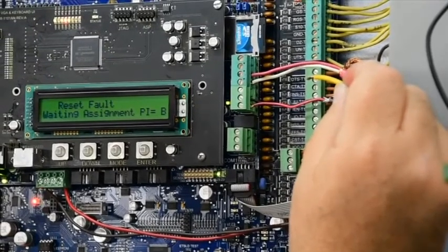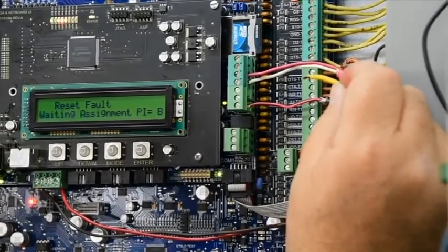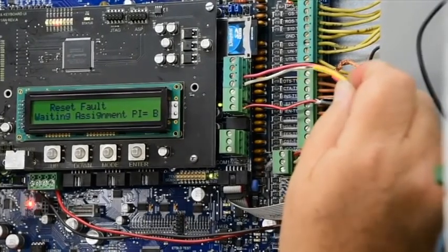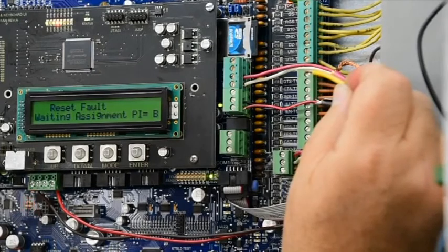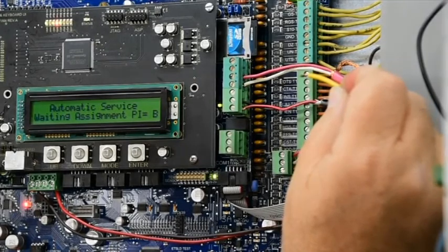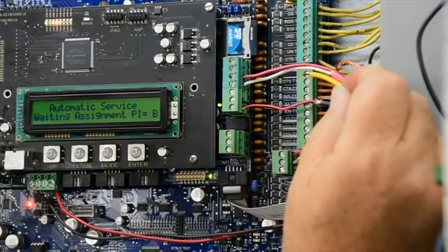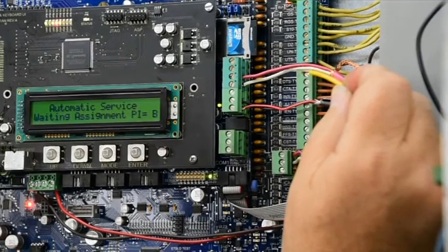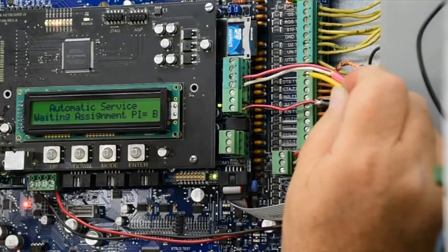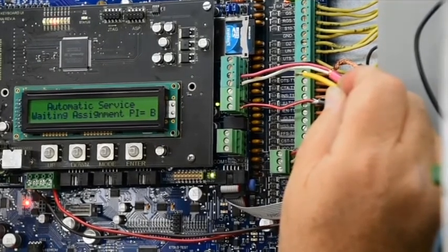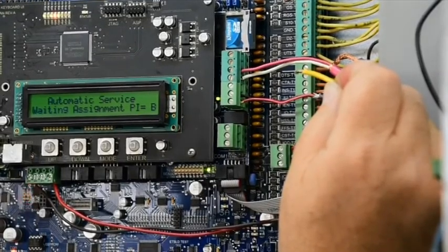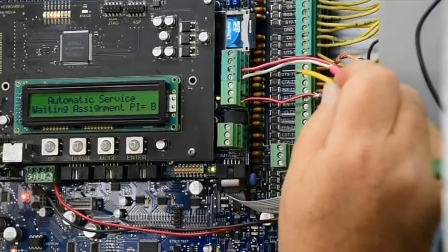We have already verified the automatic input, or the ICA. We are now going to verify, if we have 2 inputs on at a time, that the car will also shut down. Now this needs to be done with the car on full automatic so that the ICA is hot. And if you can notice, I've put one end of my jumper already into ICA, so that the jumper that I have is hot. Again, you need to be very careful doing this. There's 110 volts on the wire. Be careful not to touch what you should not.